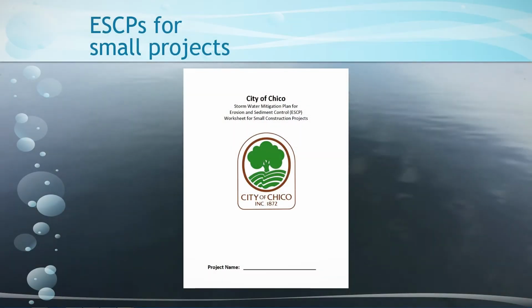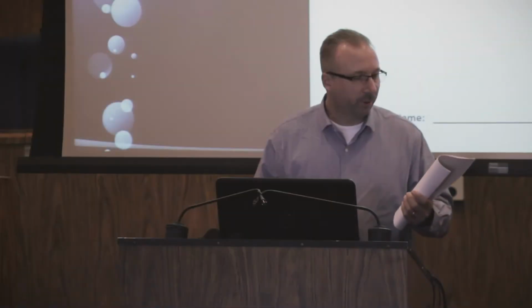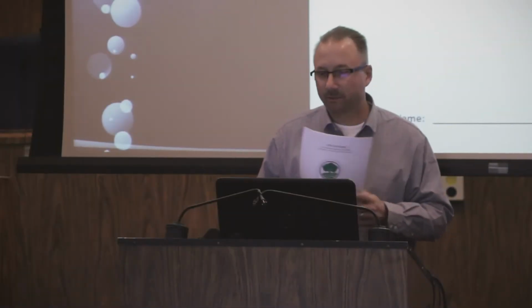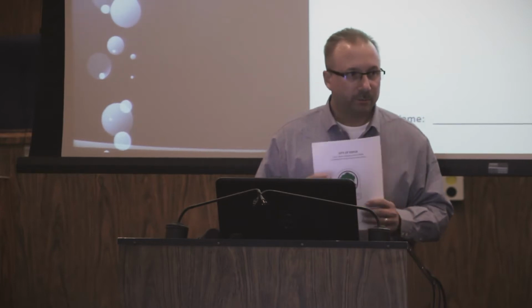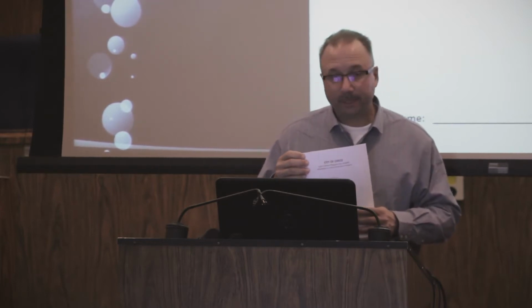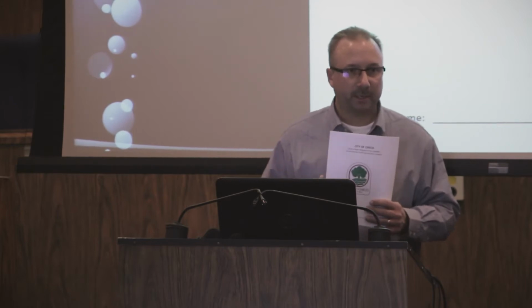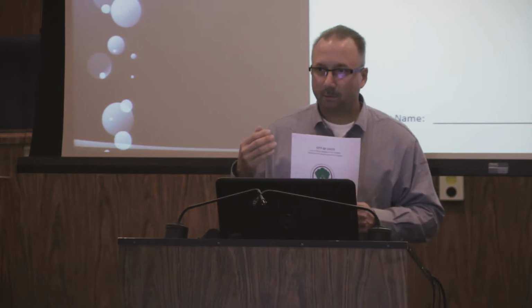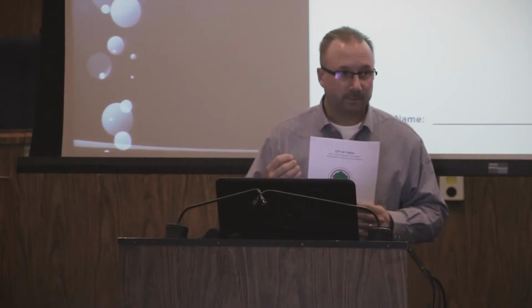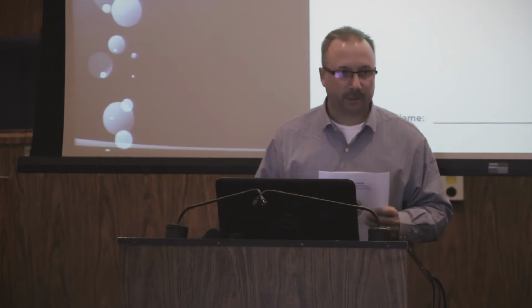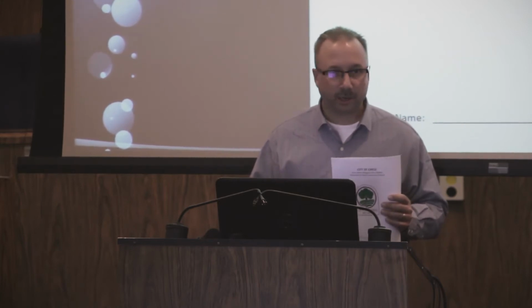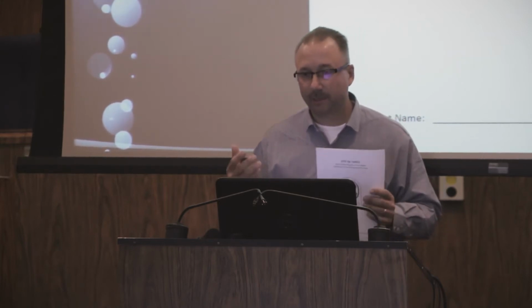And so you should have in your hands a copy of what you see behind me on the screen. This is a worksheet that we developed for small construction projects, and really this would be probably 80% of the erosion and sediment control plan submittal, in which they will identify their project and some basic information about it, like who is the owner, who's the contractor, the scheduling, sequencing, that type of thing.